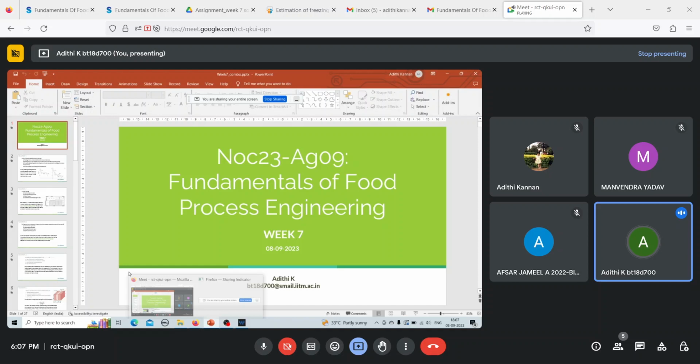So the refrigerant passes its cold temperature. The heat is exchanged from the air to the refrigerant, so the air becomes cool, and then this cold air freezes the food product further. The cold air can either be forced or naturally circulated. So you can either have a pump that circulates the cold air, or you can leave it to circulate naturally. And this blast freezing can be done either in batch or continuous modes. So the answer to this question is option C.